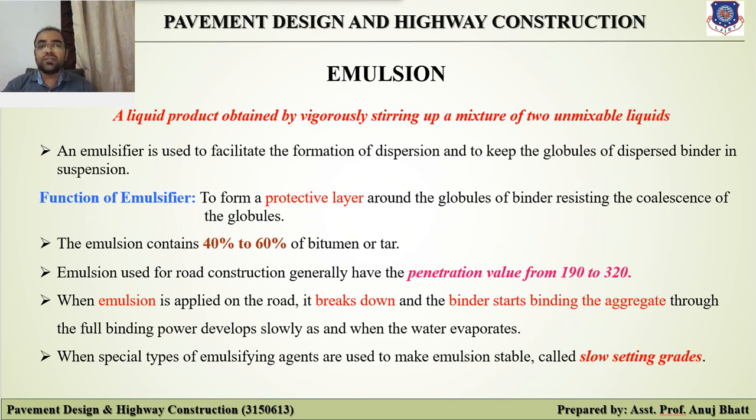Emulsions which do not break on contact with the stone but break during mixing are medium set grades, and when special types of emulsifying agent are used to make the emulsion stable, they are called slow setting grades. The manufactured emulsions are stored in airtight drums.